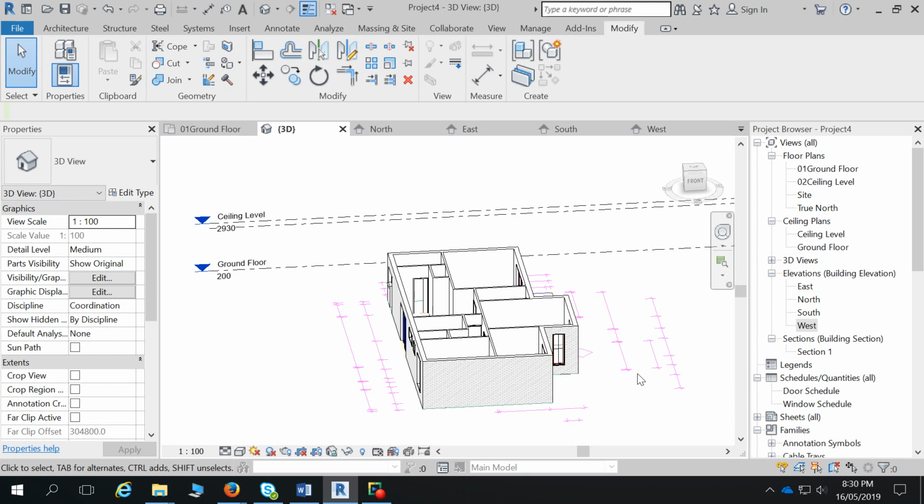I've got that line in. Yep. So select your level first. You're already in the line tool, so go and undo it. Control Z on those as well. So the line tool, just verify multiple alignment is already selected. So the first click is where you want things to end up. And then the second click is what you want to move to end up at that point.